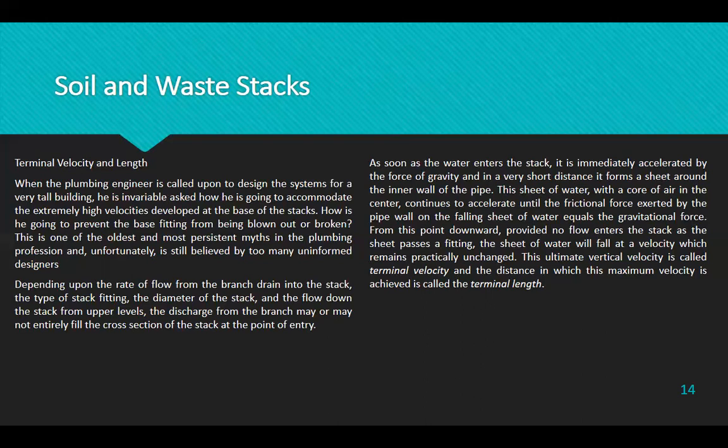This is one of the oldest and most persistent myths in the plumbing profession, and unfortunately, is still believed by too many uninformed designers. So, depending upon the rate of flow from the branch drain into the stack, the type of stack fitting, diameter of the stack, and the flow down the stack from the upper level, the discharge from the branch may or may not entirely fill the cross-section of the stack at the point of entry.